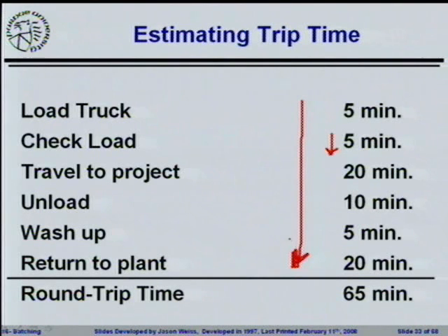And one of the things that you will find out a lot of times about ready-mix trucks that are going out to different construction sites is they migrate like pack animals. So every 5 or 7 minutes one is leaving the plant, but somehow they show up in flocks, where 5 or 6 of them will show up at a time. And most typically the drivers will show up together because they've stopped for lunch or coffee, or it was easier to stay all in CB range talking to each other. You want to make sure that they stay relatively evenly spaced as they're getting to the site. You also want to make sure that no trucks are getting out of line and jumping ahead of other trucks, because once the water hits the cement, you're starting the overall process.